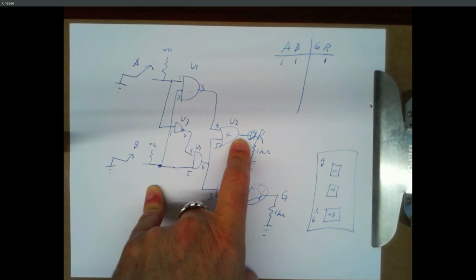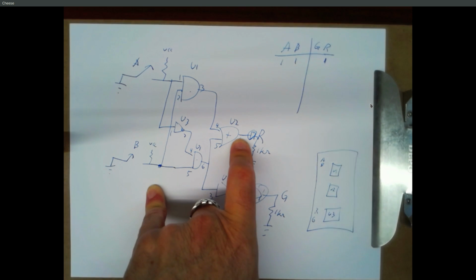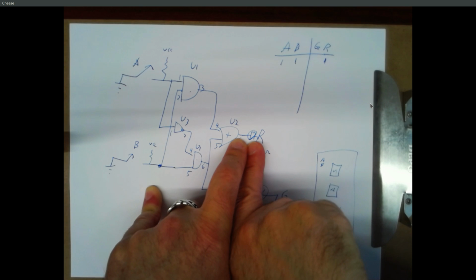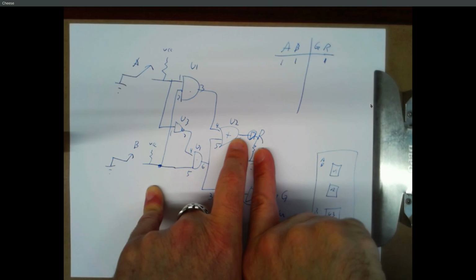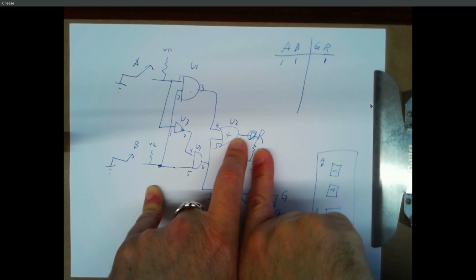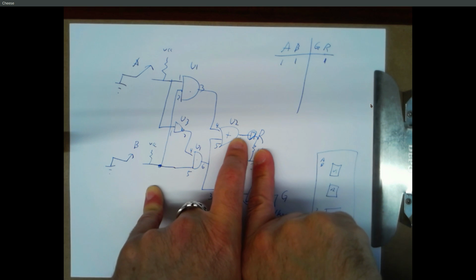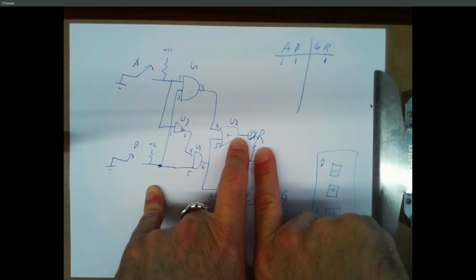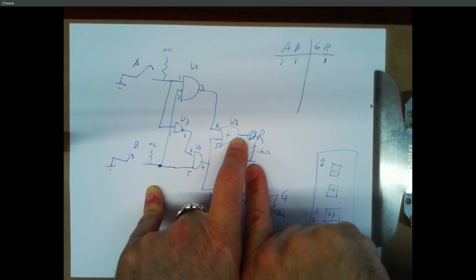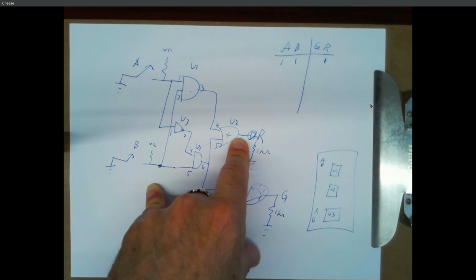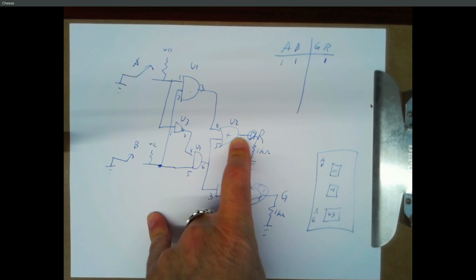Right, so you take the LED, double check the polarity, right? If the polarity looks right, stick another LED in there. If it's still not on, check your resistor. Is it actually a 1K or is it a 10K? Because a 10K looks a lot like a 1K. Right? Check the other end, is it really connected to ground? Maybe it's in a ground bus, but that bus isn't grounded, right?